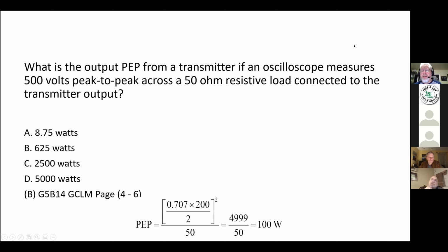The following terms apply to all components and may be important when selecting a component for a design or for repair. The nominal value is the quantity of a specific characteristic that the component is manufactured to exhibit, such as a 10 ohm resistor. The tolerance is the amount by which actual value is allowed to vary from the nominal value, usually expressed in a percentage, such as a 5% tolerance resistor.